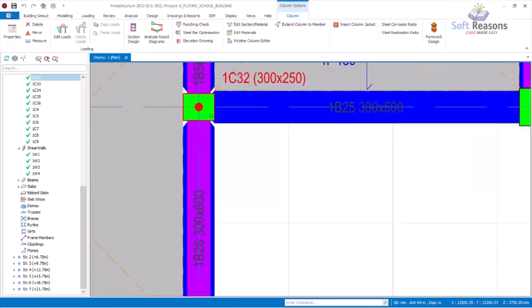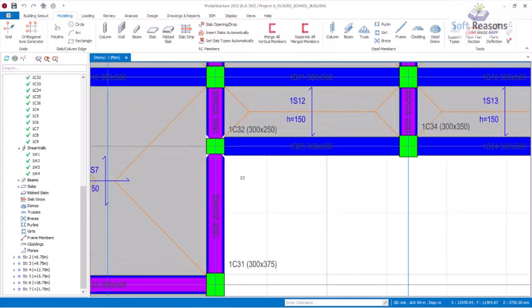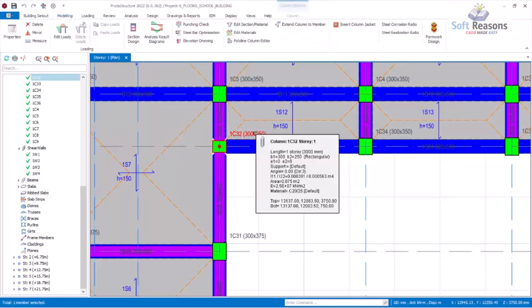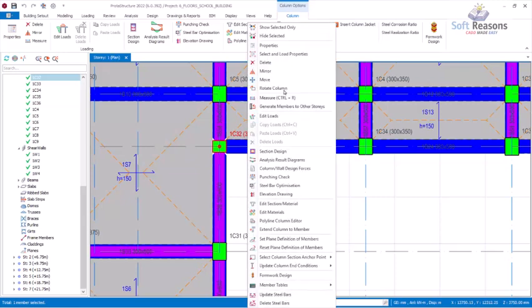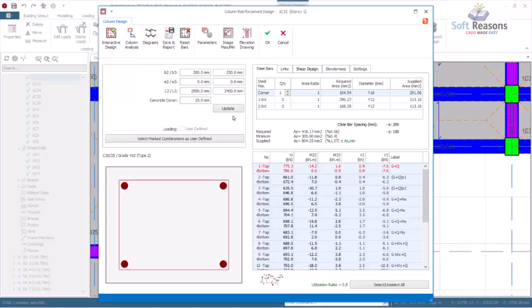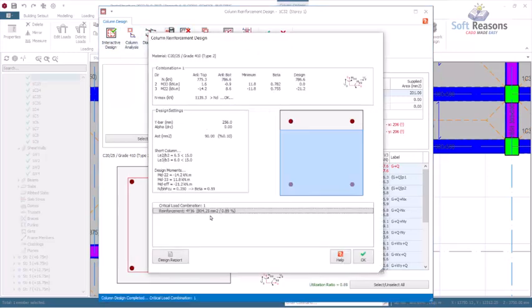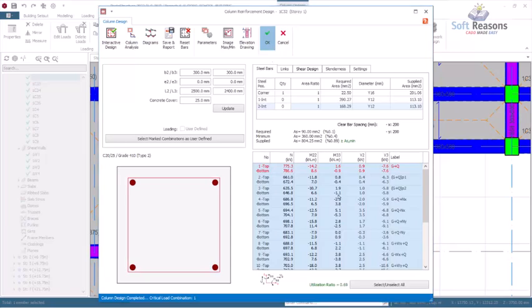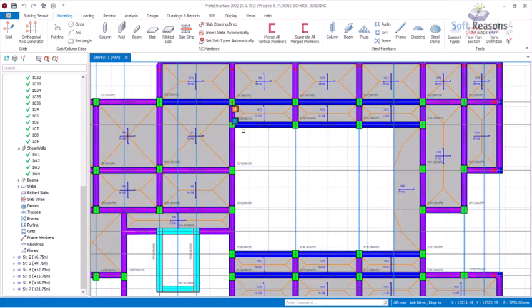So we have these columns just like this. Okay, so we will be going by 300 by 300 for the sake of the beam sections at this floor. So we select this, and then we right click and go straight away to section design. And so we have here 300 as well. We update that. We set bars directly for Y16. We go by that. Click on the OK options. Okay, so we have that successfully designed.